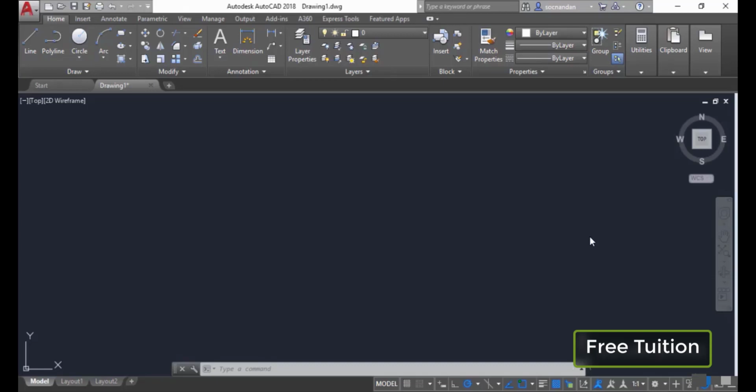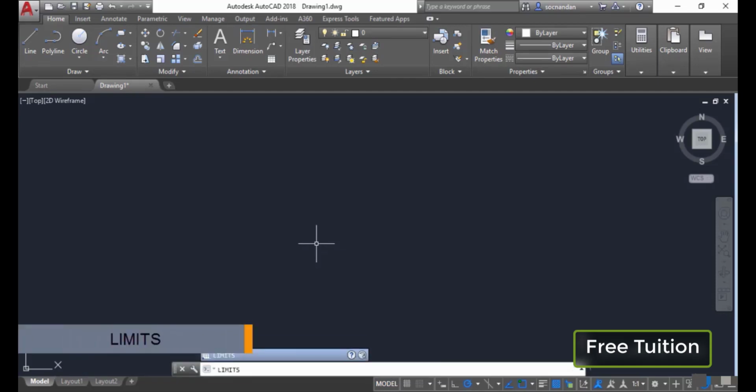So now here we have a completely blank drawing area. In the current drawing area, we don't know the extent of dimensions. For example, if you make a line of length 10 units in this drawing area, we don't know how long it will be. So in order to set that limit, we can use the limits command. So type limits and press enter.